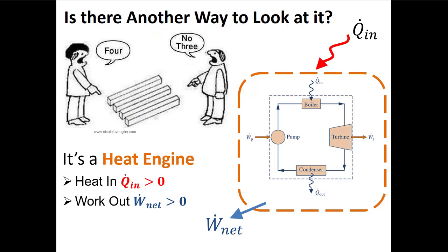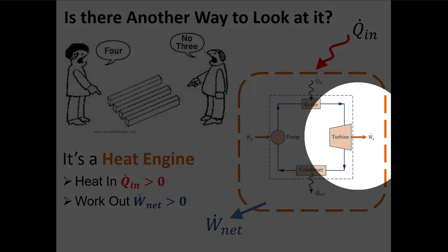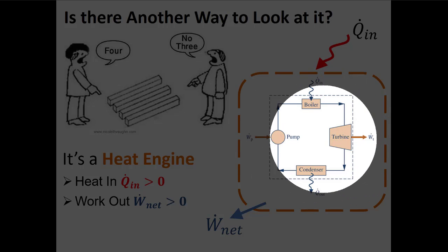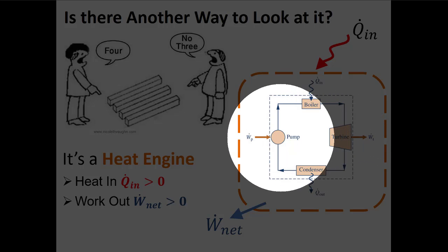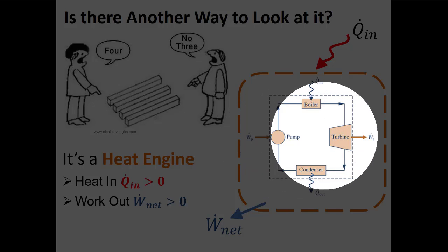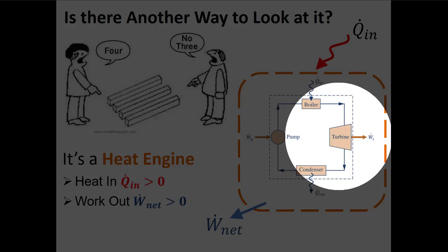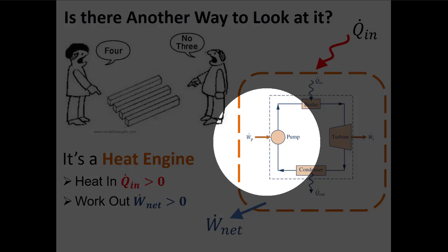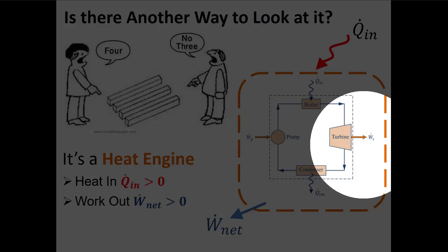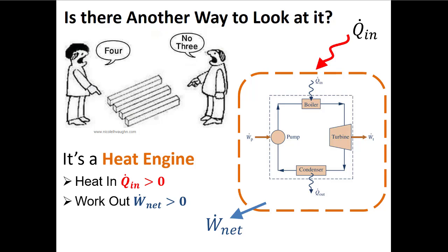Now, any kind of power plant like this, the power plant is always the first consumer of the power, because the turbine is producing some power. But in order to keep running the turbine in a cycle like this, the idea is this math just keeps going around and around and we keep generating more power, right? But in order for this to happen continuously, we also have to be running the pump. So we think about the net work or the net power, which would be the turbine power, which is positive, plus the pump power, but the pump power is negative, right? So the net work is going to be something less than the turbine power. This is when the textbook gets a little bit tricky, because right around here, up until this point, the textbook has kind of been in line with our idea of heat in is positive and work in is negative.